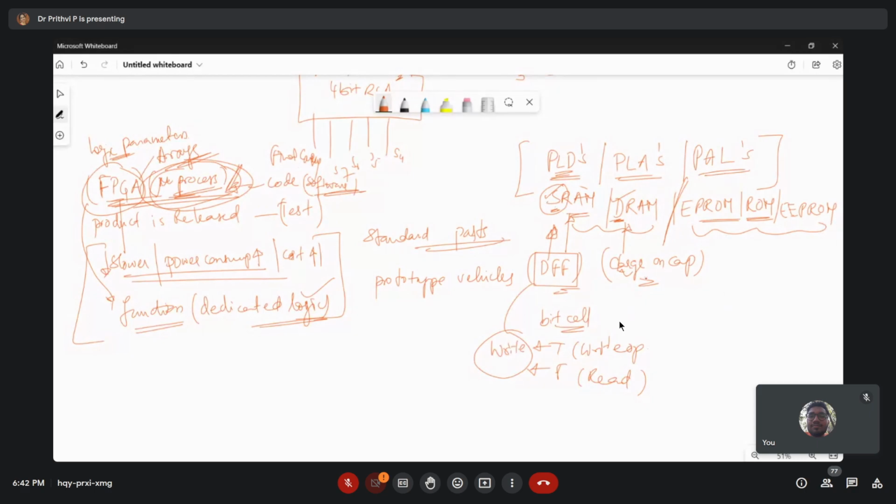For DRAM, the bit value will be stored as a tiny capacitor charging and discharging. This dynamic storage cell will be smaller than static RAM because it is a simple capacitor, compared to a flip-flop, which is comparatively huge in size.